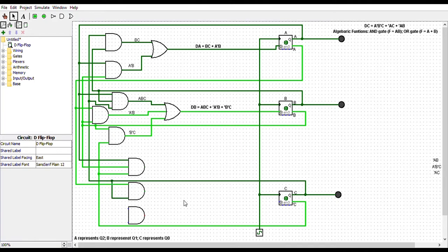Finally, we have not A and B. So again, we look for our not A wire, and connect it to our AND gate. Then we look for B's wire and connect it to our AND gate. Now we're going to add the OR gate to our canvas and then connect each AND gate to that OR gate.